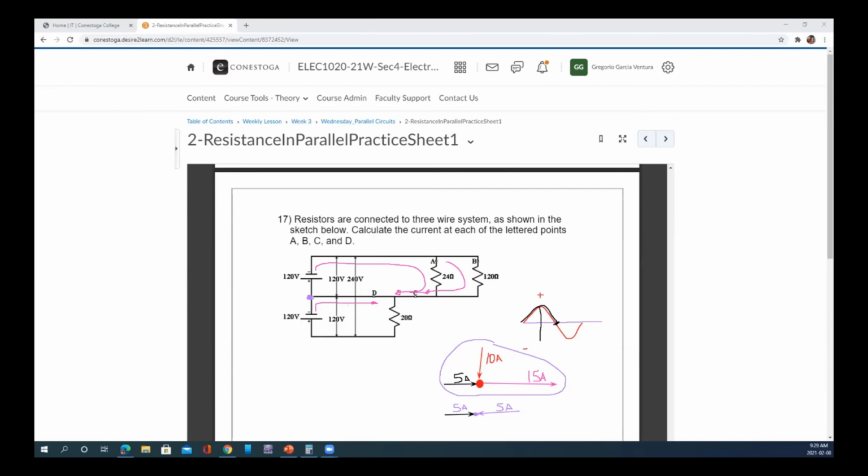So the sum of the currents that come in is going to be equal to the resultant vector that goes out. Okay, now if we have a junction point like this, and we have current in 2 different directions, they are going to be fighting each other because they are in different directions, and the resultant current is going to be equal to 0 in that case. So you are going to be using this idea in order to solve for the values of current in this circuit.